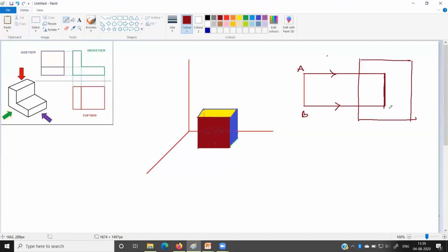Now orthographic projection is a type of parallel projection in which the projectors or projection lines will meet at infinity, and these projectors create a perpendicular. That means when those projectors fall on this projection plane, as you know this plane is called the projection plane, they create a 90-degree angle. So this type of projection is called the orthographic parallel projection.